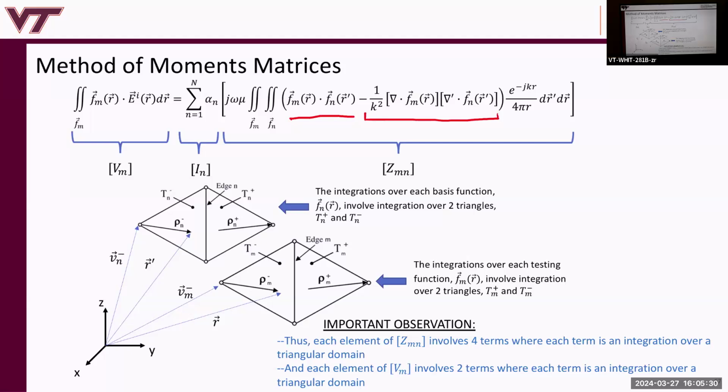If you're increasing the complexity or the order of the functions. Linear, right? So it can't be constant. So you can't use pulses, right? Remember, pulse basis functions are constant approximations, piecewise homogeneous, or piecewise constant. So that means you couldn't move these derivatives onto the basis and testing functions because you can't differentiate them. And in a sense you can, because you would end up with two delta functions that are pointed in opposite directions, that are the derivative of a rectangle function, technically. But then you have to deal with those, right?